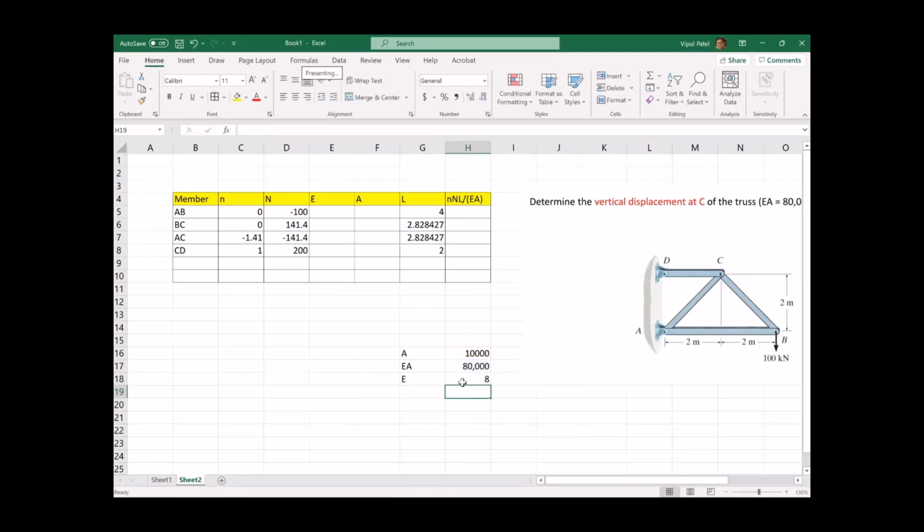I think this is very small. Young modulus, we need to get it 20,000. So let's do it another way. Young modulus is 20,000. Then area would be 4. Yeah, that's okay. So now this is dummy, by the way. So let's put 4 and Young modulus 20,000. That will make it 80,000 EA, right?